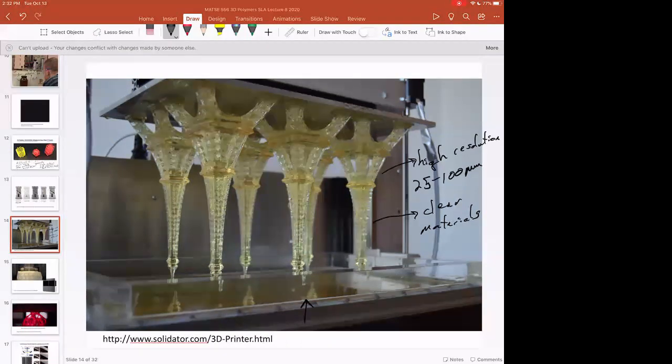You can actually print in something that looks like a carbon fiber weave into a part when it's all just plastic. Or you can print in surface roughness if it's going to be a grippy part, or print in smoothness. And so that's a technology that SLA is able to sell because they can produce parts with such high resolution that now you can print surface features into the part to give the look and feel that you're interested in.